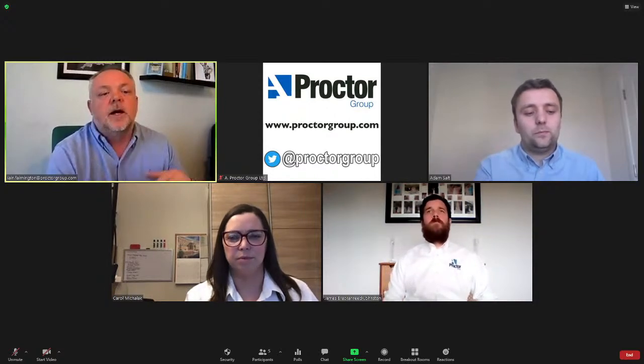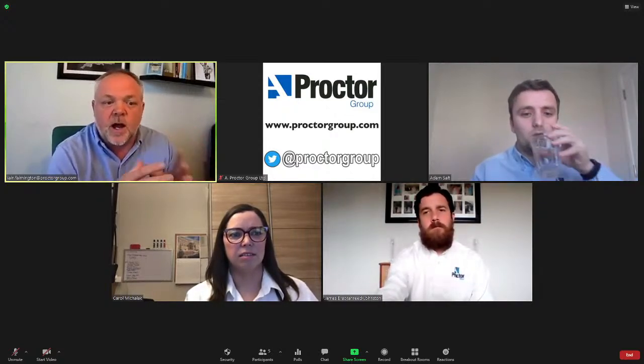So the WUFI calculation gives a much better holistic approach to the moisture in that building and how it dries out. So it's one that we would recommend for solid walls, not necessarily for a new build that's dry and doesn't have any built-in moisture, but where you do have built-in moisture, that's always a good way to go.